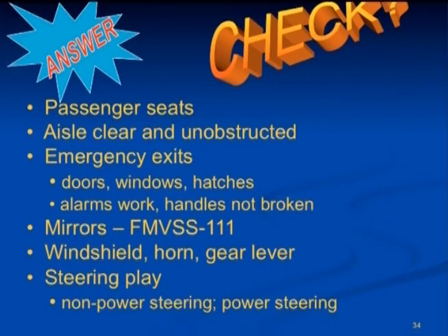Check the mirrors, they are an important part of the pre-trip inspection. It's your responsibility to adjust them according to Federal Motor Vehicle Safety Standard 111. They should be checked to be sure that they give the view required for safety. They can vibrate out of adjustment. And check the windshield, horn, and gear lever, and check steering wheel play.